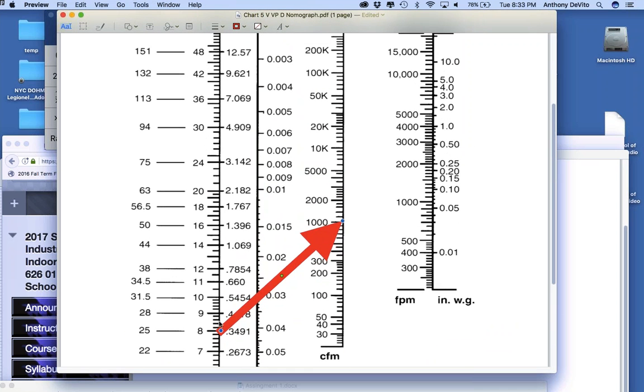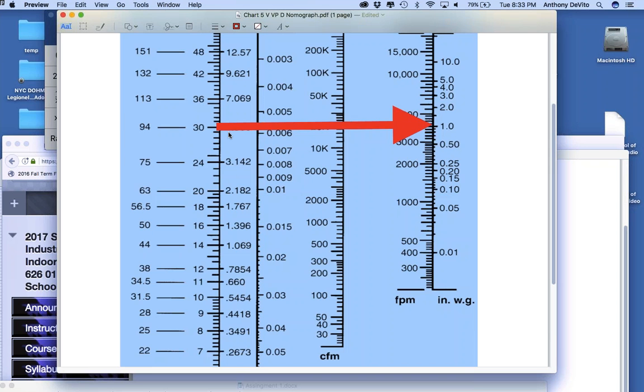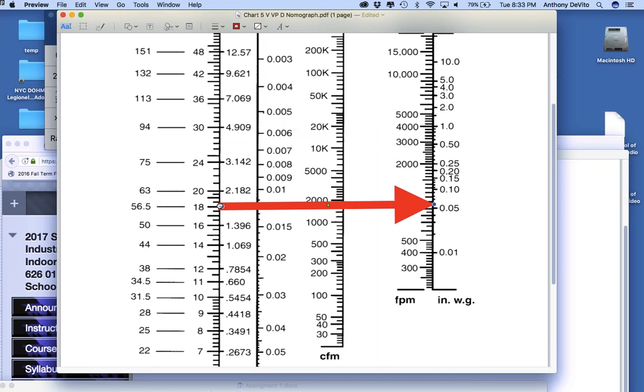Okay, and notice that as the ductwork gets larger, what happens to the K value? What happens to the K value if the ductwork gets bigger? Goes down, right? Because you have the same velocity, you have the same quantity of air going, but it's going much slower, and there's less of it in contact with the side, even with the velocity staying the same, right?